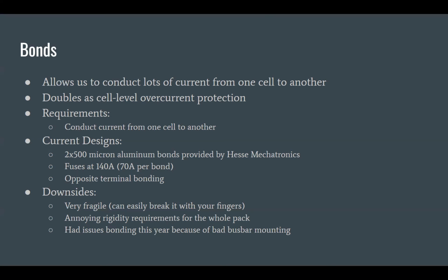You drive slow, and also we can update the value in the BMS, then it'll require less current draw. So 80 times about 600, that's only 50 kilowatts. So we would have half of our power budget stripped out, which means we basically wouldn't be able to go at any higher speeds than 40 or 50 miles an hour, and past 20 or 30 we'd be pretty torque limited. That's not great, but we would still be able to drive competition and do our thing.